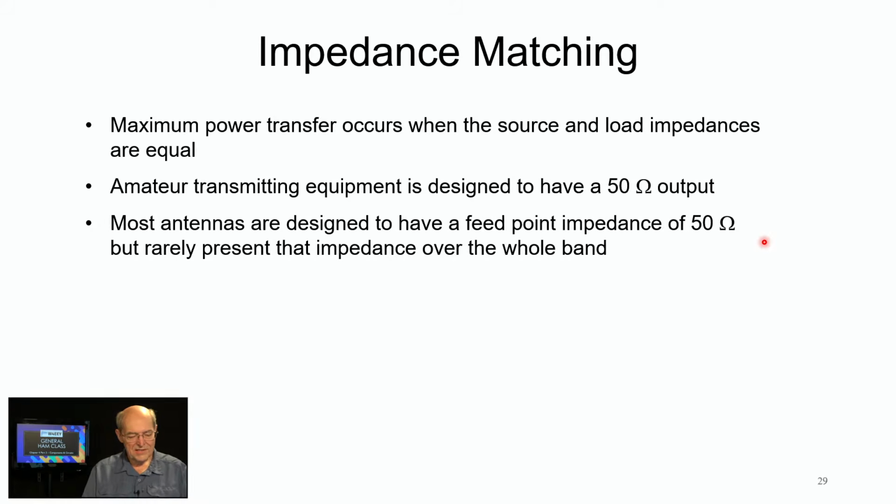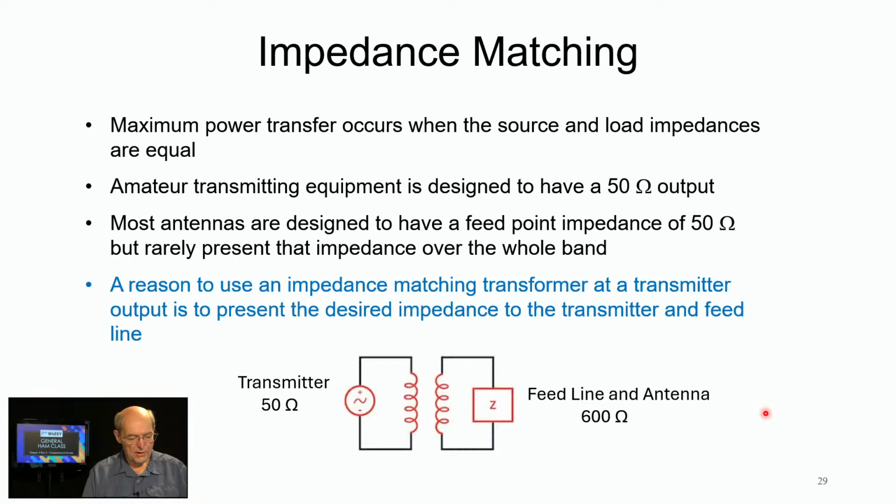And the reason this is important, the reason we're getting into all of this, is because modern transceivers will, if they sense a high SWR due to a mismatch, start folding back the power to protect the transmitter. So that's why this is important.